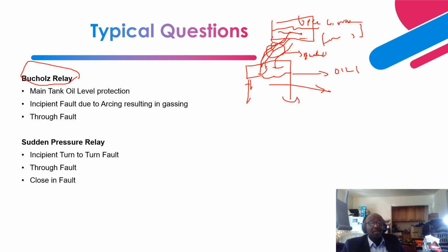And sometimes, if the transformer has been in operation for 20 years, 30 years, based on its location, if it is in a very harsh, corrosive environment, and also due to degradation of the transformer seals, basically the interface of all the mounting devices and auxiliary devices with the main tank, they will degrade. Now, you see that the oil will leak through all these joints, so the oil level is going to go down.